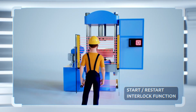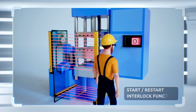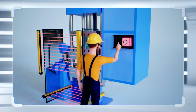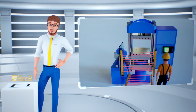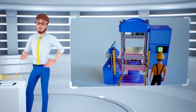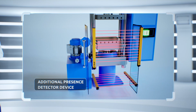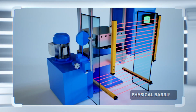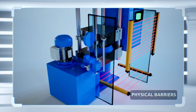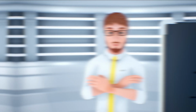Positioning the restart button in a position that allows the full visibility of the dangerous area and where it cannot be reached by anyone from inside the dangerous area. Use of additional presence detection devices within the dangerous area, for example, light curtains used as presence sensing devices. Use of physical barriers, preventing the operator from accessing the dangerous area without being detected by the safety device.